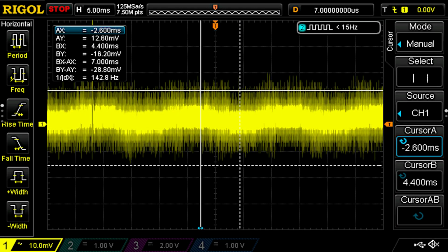And now the voltage that goes to the AVDD pin of the microprocessor, the voltage that powers the ADC circuit. This is not near as clean as I was hoping for. And that maybe 5 millivolts 60 cycle that wouldn't be a problem on the main 3.3 volt rail could be a big problem here. The least significant bit of the 12-bit ADC should have a sensitivity of less than 1 millivolt. I'm not sure what I can do to clean this up.